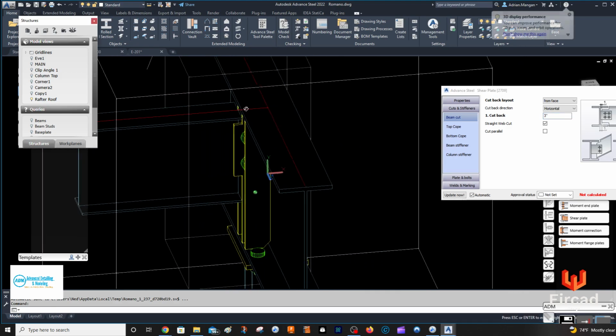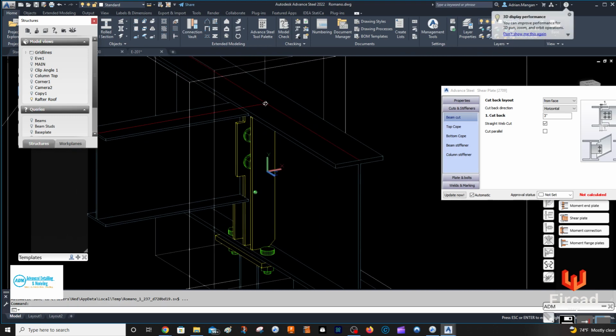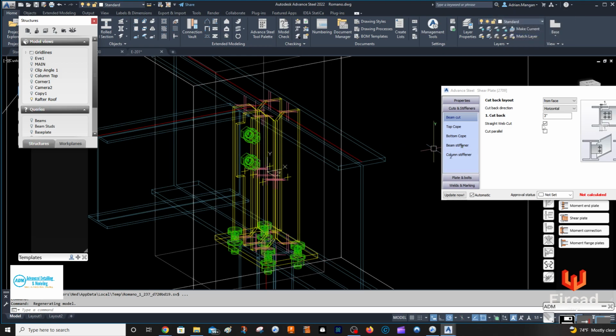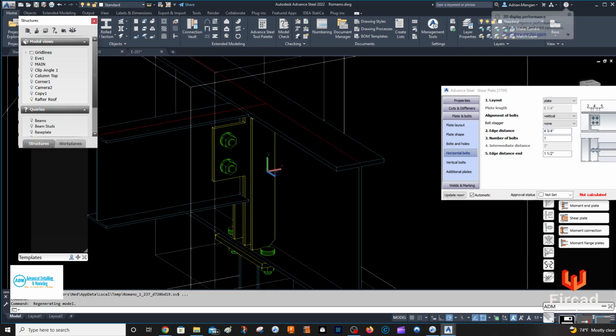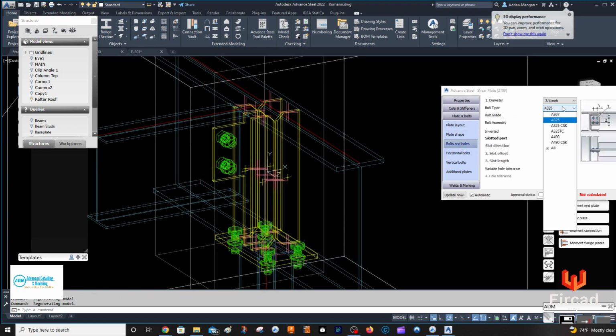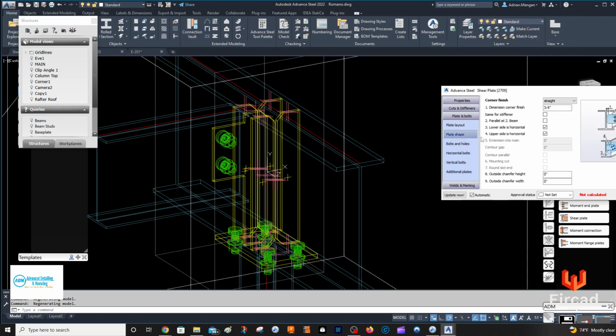And that gives me, it doesn't matter, it just gives me a gap that's around 1/4 or 1/2, and that's what I want. I just want to have a number here that I can work off, because I need my bolts to be back in at least 4.5 now. But I'll just go a little bit more, so I'll go 4.75. And then I want to change the bolts to TC bolts. There's a lot of other options here, most of them you won't use.